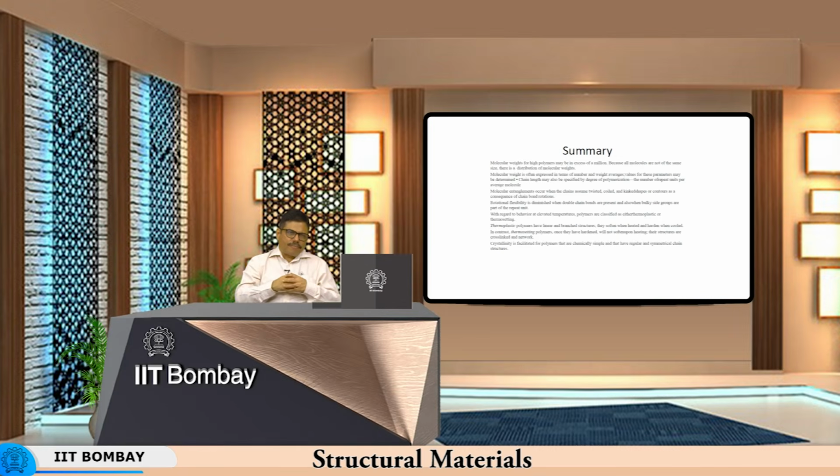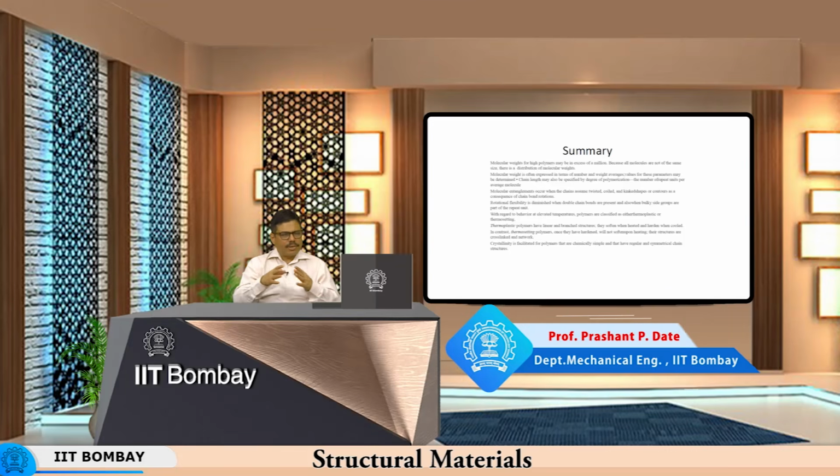Now if there is no chemical change undergone by the material, as in case of thermoplastics, then the internal atomic attractions, chain structure, etc., will play a role in deciding the mechanical behavior. But if there has been a chemical change in the polymer, as in case of thermosetting polymers, then the chemical change resulting in cross-linking determines all the properties that we see. So there is no question of softening, no question of any ductility, and no question of any movement of chains relative to each other.